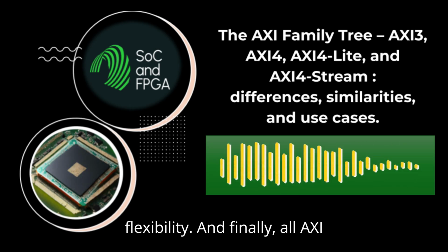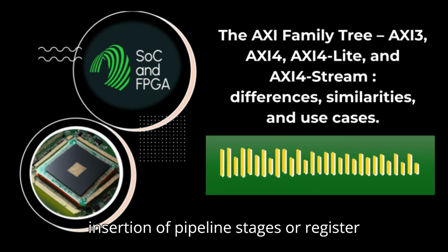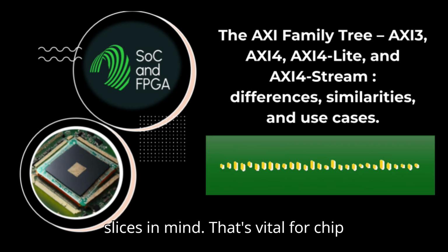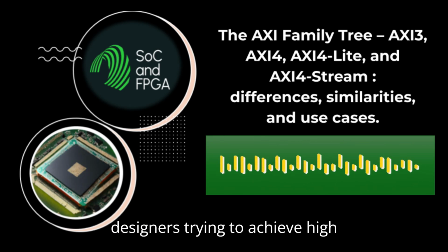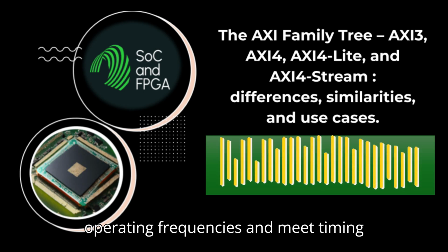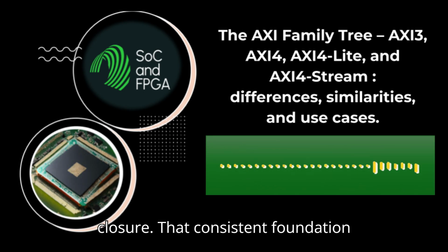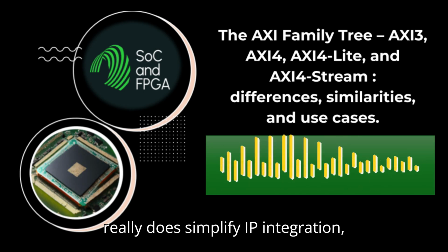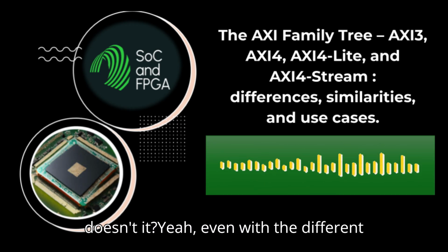And finally, all AXI protocols are designed with easy insertion of pipeline stages or register slices in mind. That's vital for chip designers trying to achieve high operating frequencies and meet timing closure. That consistent foundation really does simplify IP integration, doesn't it? Yeah. Even with the different functions.